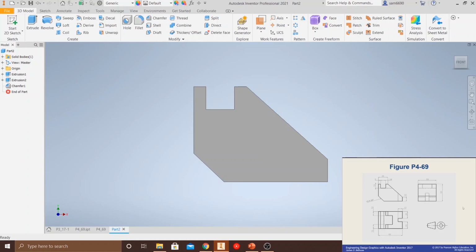Now, let's look over here at this drawing again. You can see that these are hidden lines. These lines right here. So, what this is saying, looking at these different views, this is our left view, okay, and this is our top view. This is saying that this cut here goes all the way through to this part. So it starts right at this part right here. And then this cut on this left view that you can see is this cut right here on the top. And it's saying that it's going all the way through this top. And it's saying that this is a length of 12.